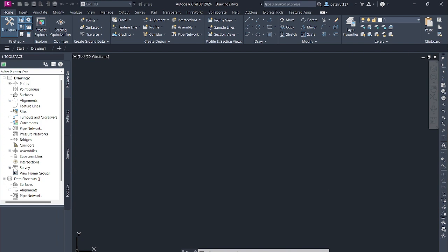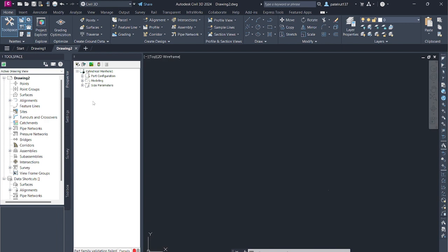Expand model parameters and size parameters. Note that there are entries listed for the work plane offsets, structure parameters and body diameter dimensions. Right-click Size Parameters and then click Add. The Edit Part Sizes dialog box is displayed, along with the new parameter dialog box. Select Structure Riser Height 1 and press OK. A new parameter of SRZ1 is displayed in the Edit Part Sizes dialog box.